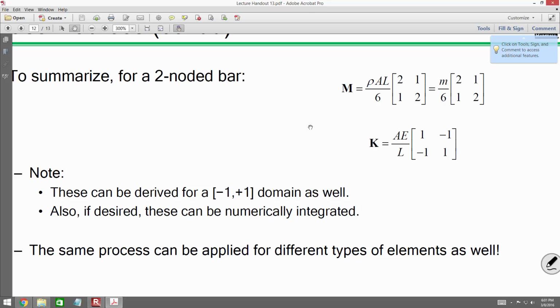For us, however, where we're trying to do it a little more consistent and more with a finite element approach, consistent mass matrices seem to make more sense from a derived standpoint. But it's your choice as the analyst what approach to use. And you can actually split the difference. You can say, here's a consistent mass matrix, here's a lumped mass matrix, let's just take the average. That's actually a valid theory within the world of finite elements as well. It's all about what you're doing and why you're doing it.